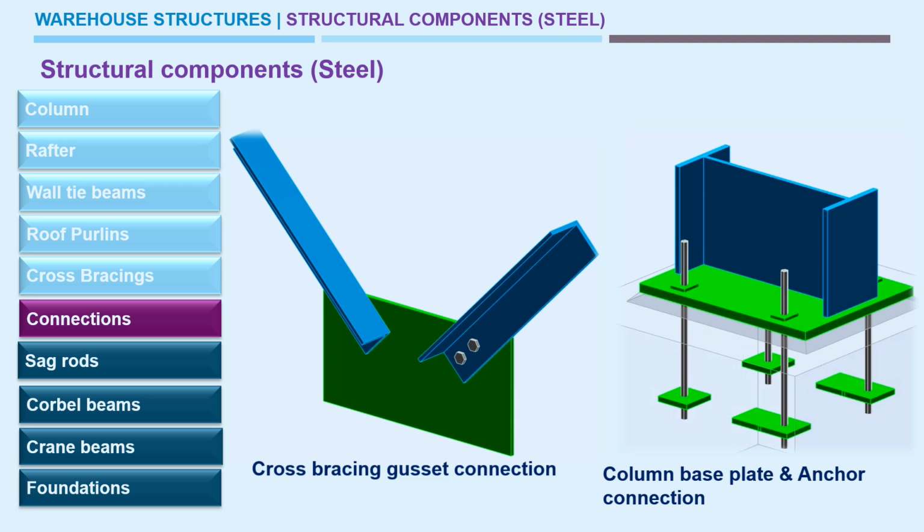In this way we find the bearing area, which resists the load transferred downward from the structure. By this way we arrive at the size of the base plate, and the thickness of the base plate can be arrived at from the lever arm distance and the support reactions from the concrete or the anchor bolt. By these two ways we can analyze the base plate thickness.